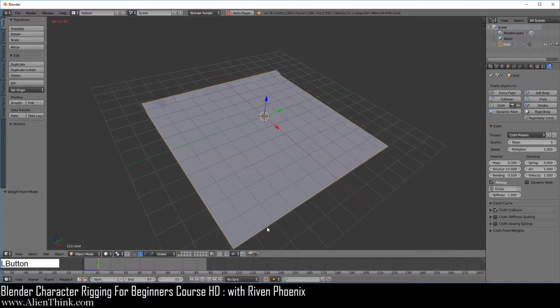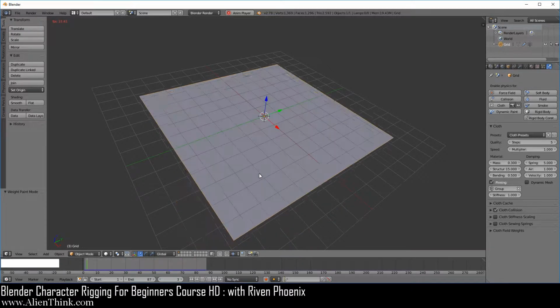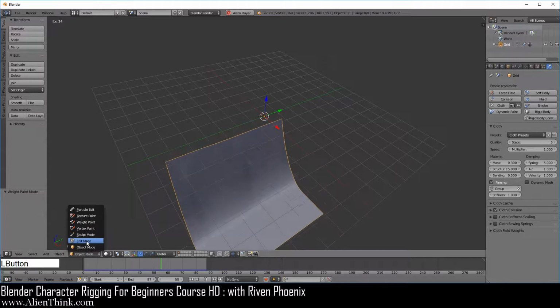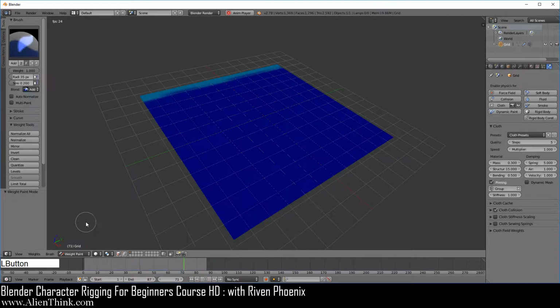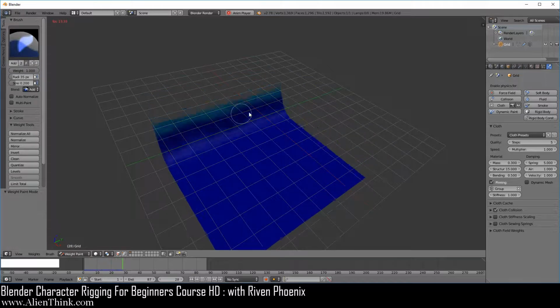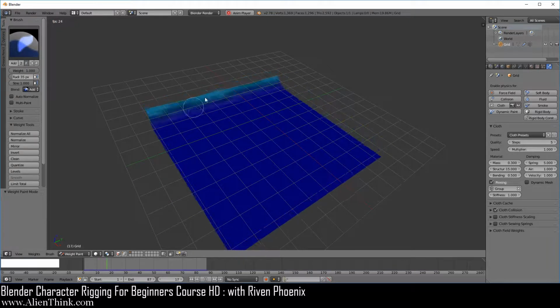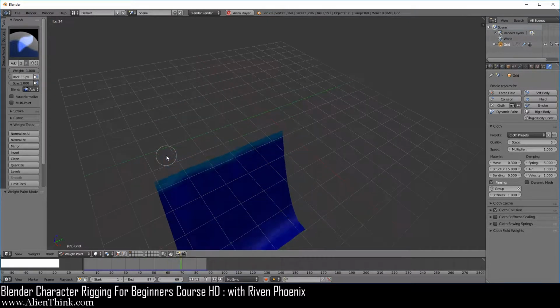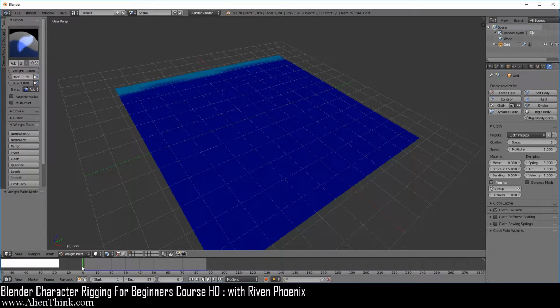Click on play. So you'll notice that what that's doing is creating a cloth simulation. It's just going to keep resetting. Now when you switch to edit mode, you're not going to be able to see this, but it just so happens when you click on weight paint, it will reset. So now what we're going to do is increase the strength over here on 1. Take a look at what happens when we just zoom in. Okay, go ahead and stop this and actually take it all the way back.